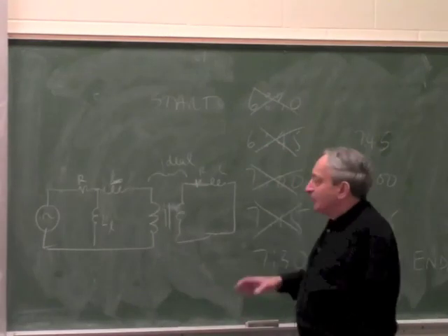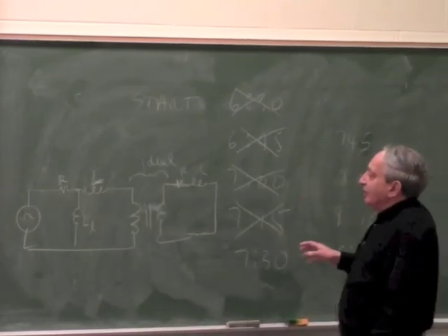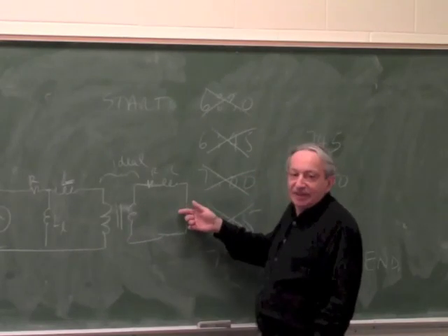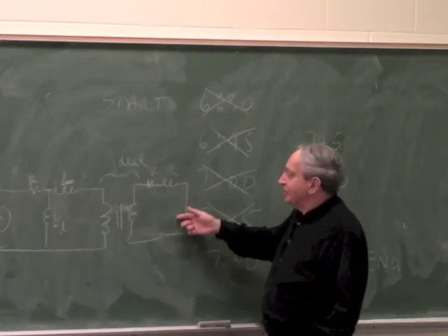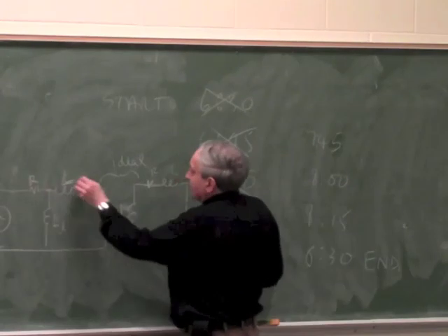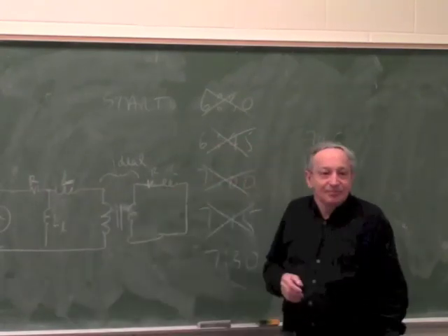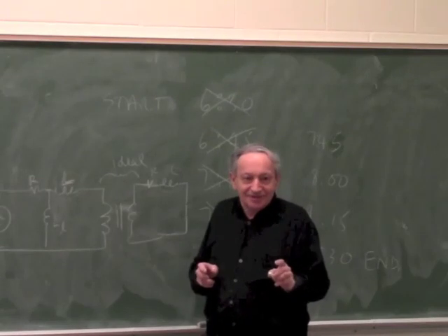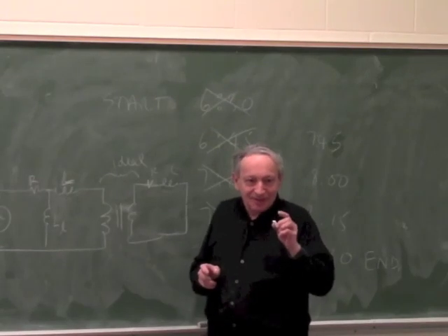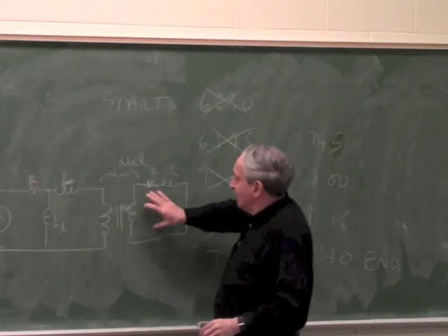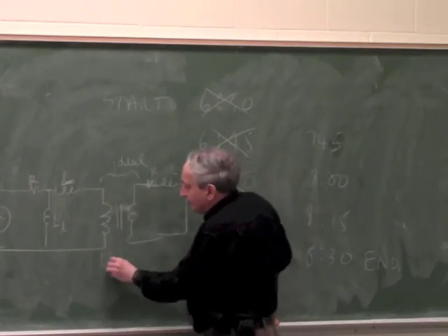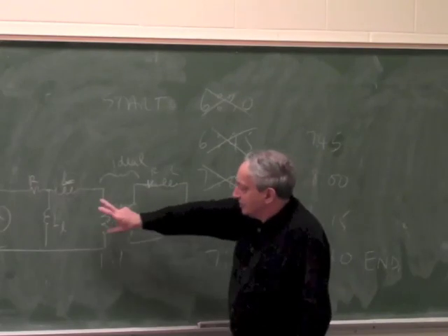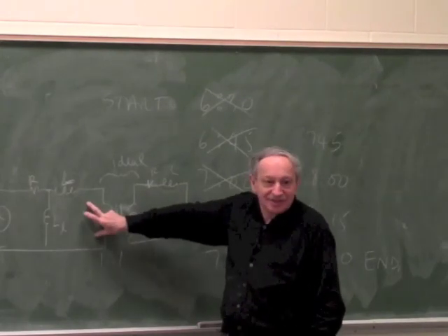So when you look at the model of a transformer, if you increase the frequency, this current not necessarily gets higher. Because you increase the frequency, this becomes a concern. Because an ideal transformer has no inductance. You have to think about this for a moment, because an ideal transformer just reflects this resistance. If this was a one-to-one ideal transformer, and you put a resistor here, you just see the same resistance on this side, you don't see inductance.